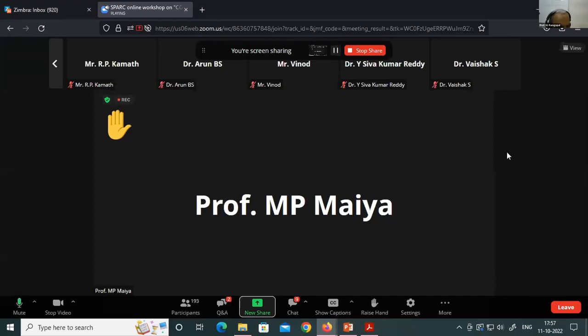Remember that we are also using an ejector. With an ejector, the intermediate heat exchanger is not always beneficial, because what is going into the ejector is a low enthalpy fluid. But I agree. What is the efficiency of the ejector you have assumed? As I have shown you, if it is 20%, then the IHX will be useful. If it is more than 30-40%, the IHX may not be useful.